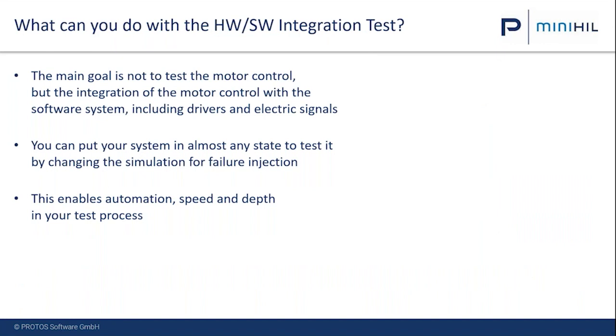What can you do now with this hardware-software integration test? So the main goal is not to test the motor control itself, but the integration of the motor control with the complete software system, including all the drivers and electric signals. So you can put the system in almost any state you want to test it. And by changing the simulation, you can do failure injection. So this enables the complete automation, thus giving you speed and depth in your test process.